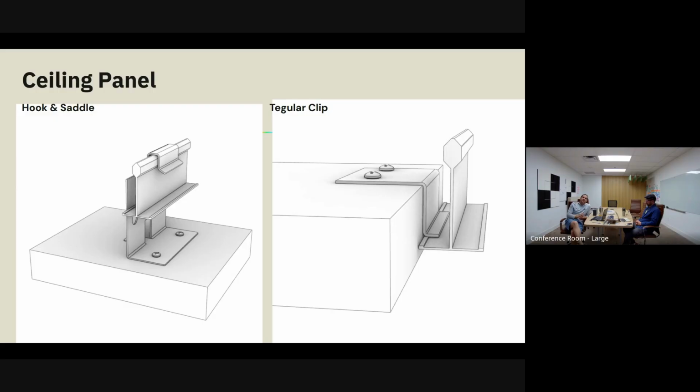So they have to do their mains on 2-foot centers. Whenever we do shop drawings for this, we always include an overlay of the grid and say, this is how you have to lay your grid. And if you don't lay your grid this way, you're going to run into issues. So it's all part of the shop drawing process. Panel sizes on these are limited to 2x4, and that is it. No variation on the panel sizes.